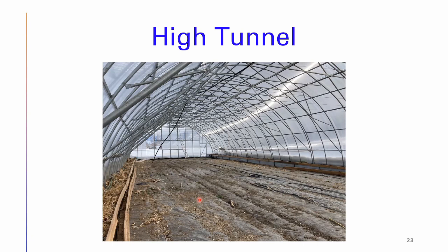So what happens is the water, the steam, the vapor in your air, it'll condense on your glazing, and then that will freeze. Now, the reason I bring that up is that it protects your plants. That energy is being sucked out of the air, not your plants. So even though you could have a 32-degree temperature in a greenhouse, you still are not necessarily going to freeze if you have large volumes. So it's kind of an interesting concept that's worth discussing.